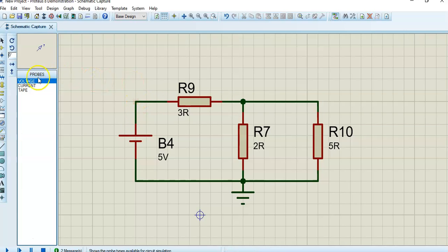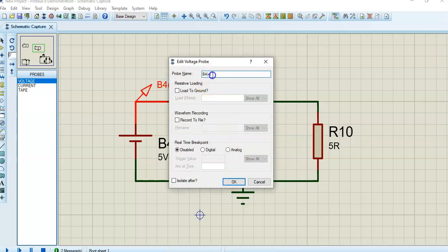Where I'm going to place one, you just click on the voltage probe and move the mouse. You get this pencil icon. That means you're in the drop mode. Again, as I mentioned before, these type of words like pencil icon and drop mode you learn by reading this help text. I'm going to place a copy here, and it automatically gets a name. Now this name B4 corresponds to the nearest component for this voltage source, that is the battery 4 here. You can always go and change this name. Just double click, and you can change that B4 plus to say B80.